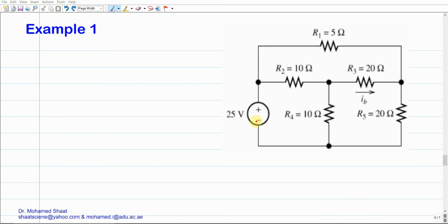So if we consider this example here, what would be the first step? If you see an electrical circuit with this shape, basically, it means that intuitively it is preferred to use the node voltage analysis method over the other method, especially the equivalent resistance, because you would find it difficult to find the equivalent resistance for this electrical circuit. Okay, anyway, we can find it, but it would be somehow difficult, and that's why it is preferred to use the node voltage analysis method.